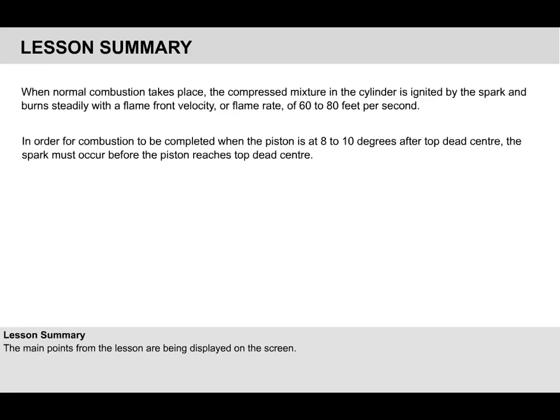In order for combustion to be completed when the piston is at 8 to 10 degrees after top dead centre, the spark must occur before the piston reaches top dead centre. The mixture will burn faster if it's made richer, or if the pressure in the cylinders increases.